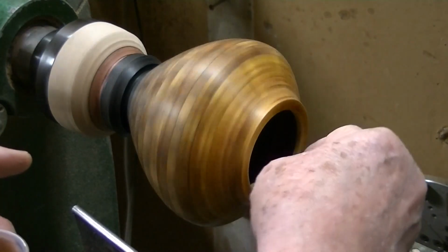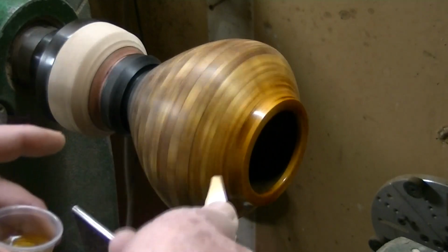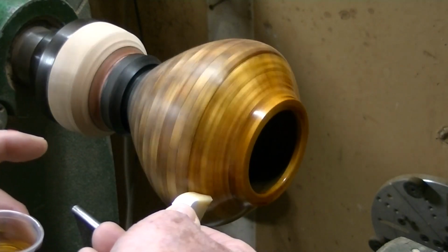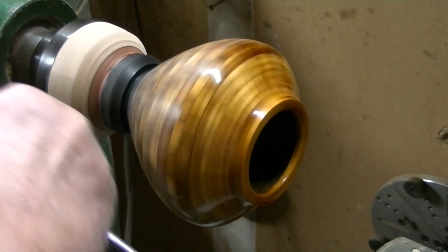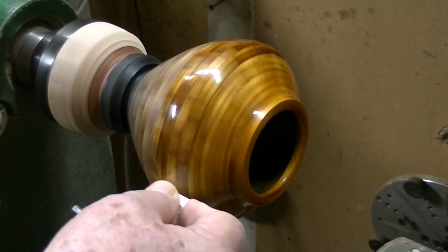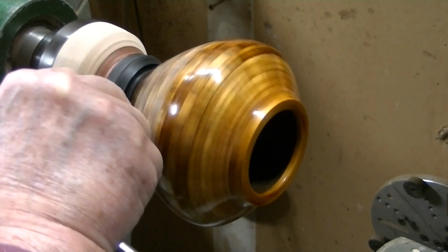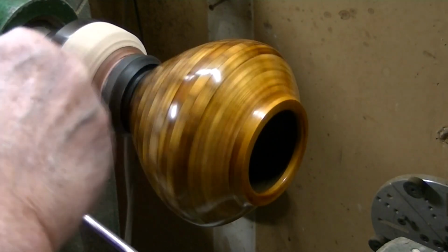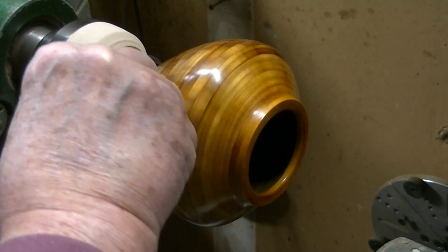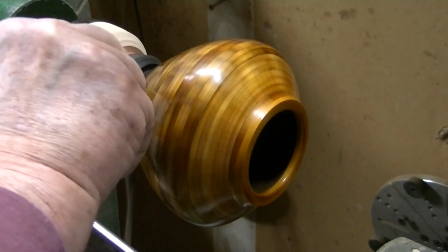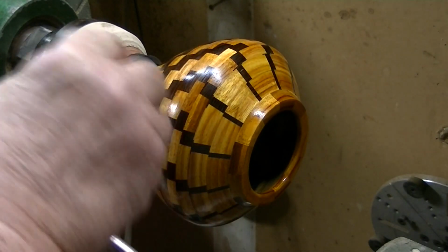It depends on the wood. If it's very porous, I may do more coats. If it's very dense wood, I might even do fewer coats. But typically 5 to 8 coats in this process. Apply a coat, sand, apply a coat, sand needs to be done. In the winter here in Northern California, sometimes that's a couple of days between coats due to the moisture content in the air causing the finish to dry much more slowly. So here's the final coat going on, and we'll spread that around. We're going to allow that to dry.